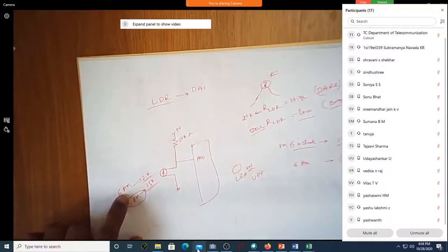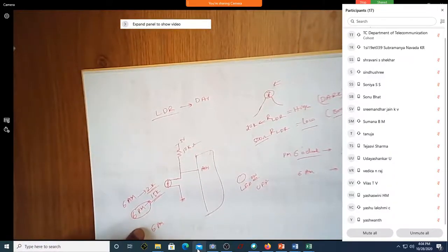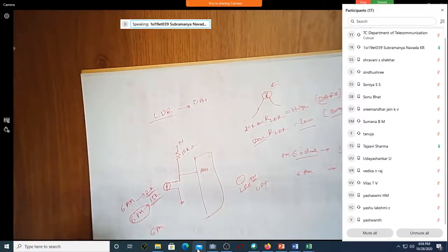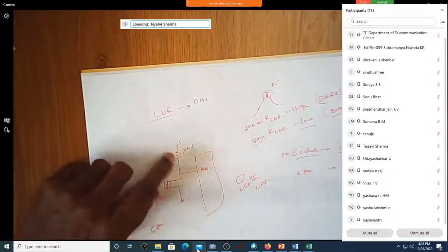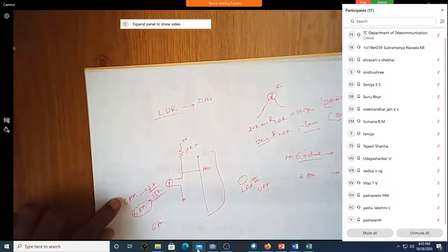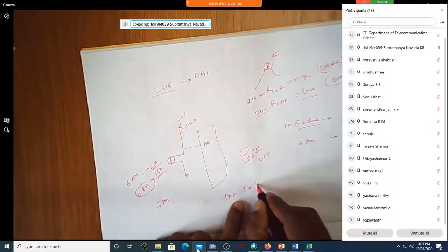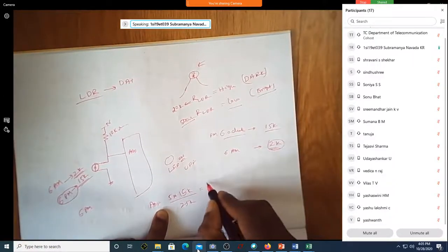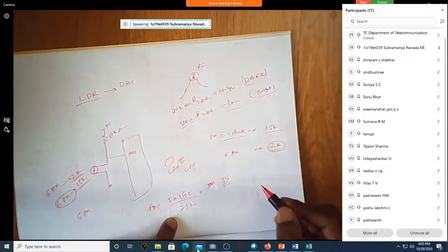So at 6 p.m., what is the A0 value? It's an analog voltage. 15K is the resistance of the LDR. I'm asking what the A0 value is for this circuit. A0 is equal to 5 times 15K by 25K, which is 3 volt. Yes, sir. This is 3 volt.